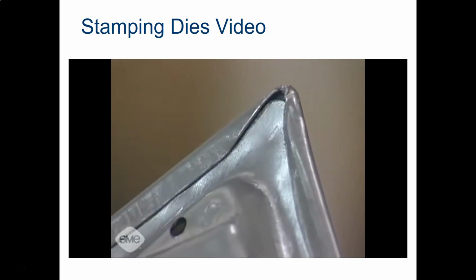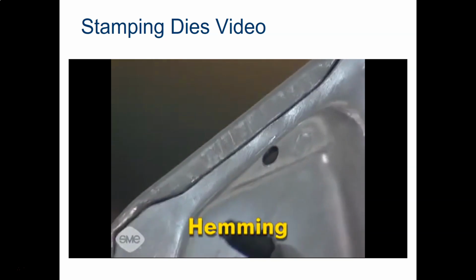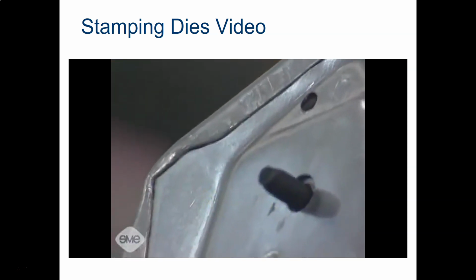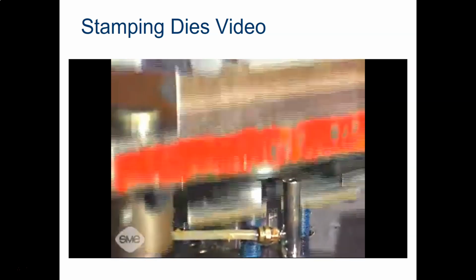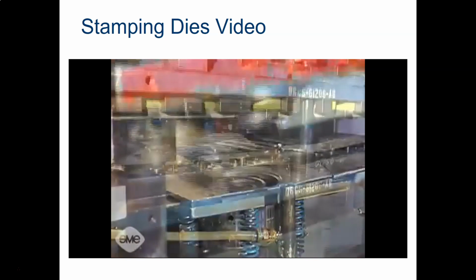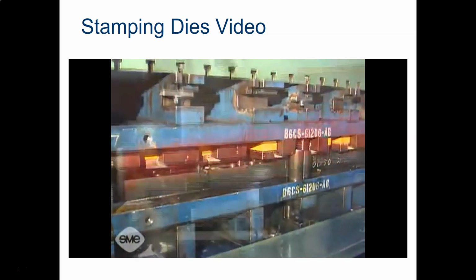In sheet metal forming, hemming is utilized primarily to provide a smooth, rounded finished edge, and to attach sheet metal parts together. Multiple operations may be carried out on sheet metal stock either at a single die station or at multiple stations within a single stroke of the press.